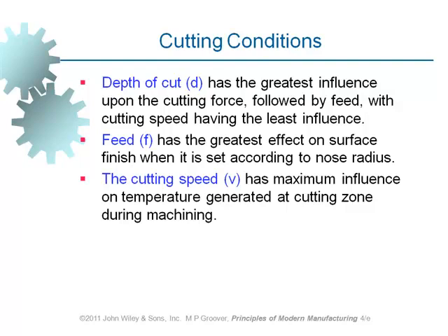And about the last machining parameter, which is cutting speed. How do we decide cutting speed? Cutting speed has a direct relationship with tool life. That's what we had in the previous slides. Okay? The rule in industry for selection of cutting speed is choose highest cutting speed, giving you desired tool life.